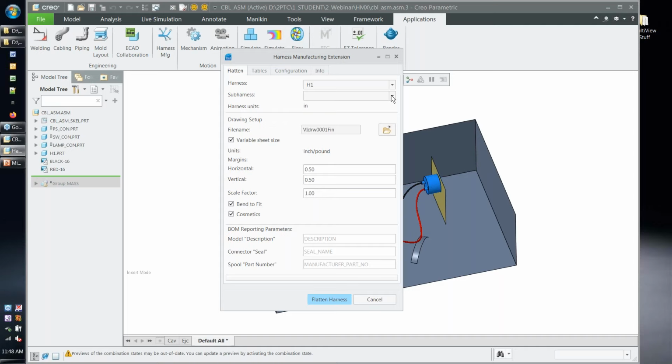Users do need to deploy a specific config.pro option if you are switching between English and metric units in your documentation frequently on the fly. It relates to the English/metric context that Virtual Interconnect, or if you will, HMX, is paying attention to. In my own work, if I'm demonstrating something in English units and I have to switch over and demonstrate something on a metric file, I simply load a config.pro that only changes that one configuration option, which makes the templating understand what I'm doing here.